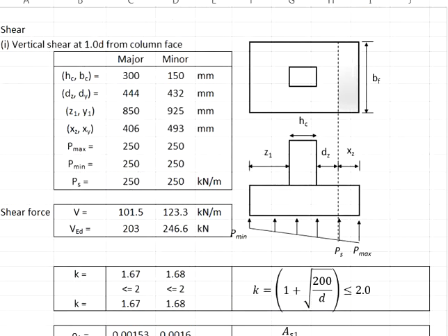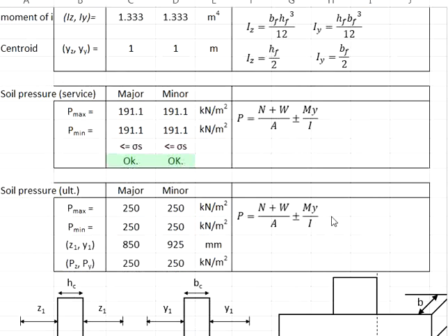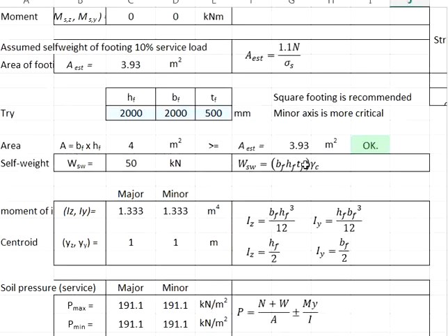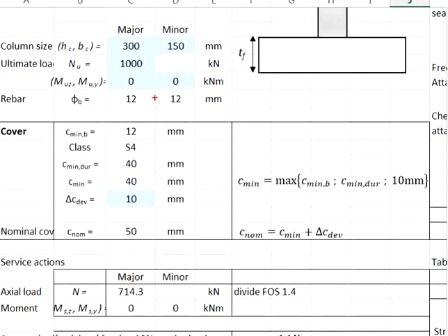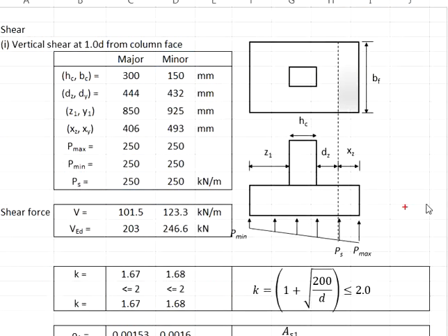And then we need the bearing pressure due to the soil. This we also calculated previously from the equations to determine the ultimate soil pressure. Since the pad footing is only subjected to the axial load without any moment, that means the soil pressure is going to be uniform throughout the contact surface area.